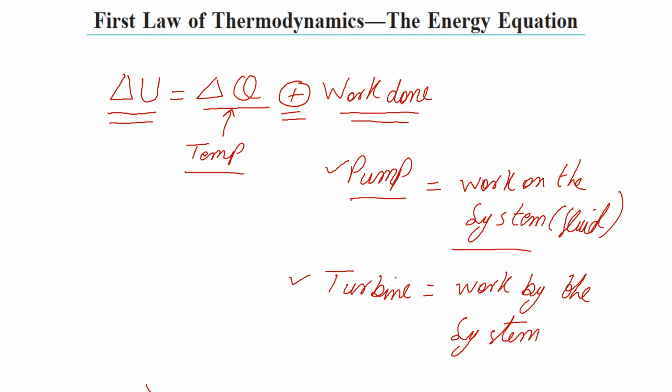That energy is again not created or destroyed, but it is transferred to some shaft, and that shaft in turn drives a generator, and it produces electricity, and in this case the electricity turns the pump, and that pump in turn adds energy to the fluid to move it from low potential to high potential. So this is the work done on the system and work done by the system.